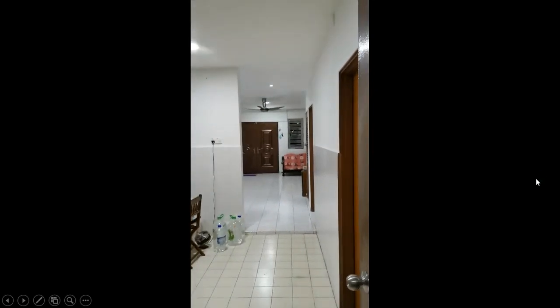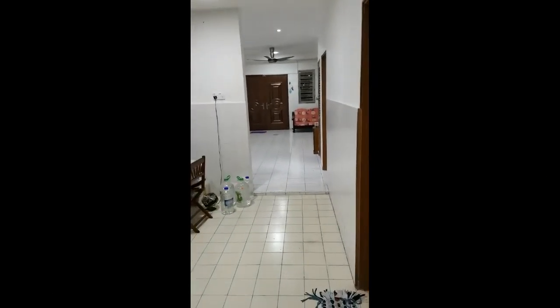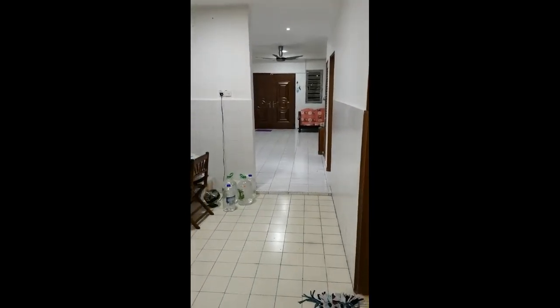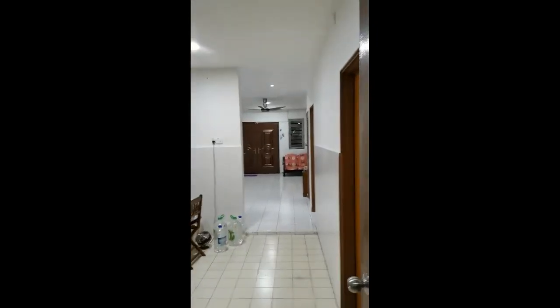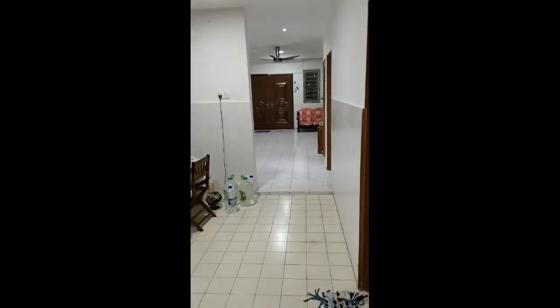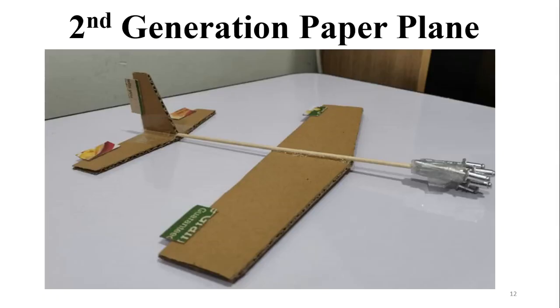As you can see, I realize the plane is unable to fly well sometimes, and if you observe carefully, you will see the wing tends to bend upward when in the air. This might decrease the lift as the effective wing surface area becomes less. So, I think I should find a better material that is stiffer than the grey cardboard.